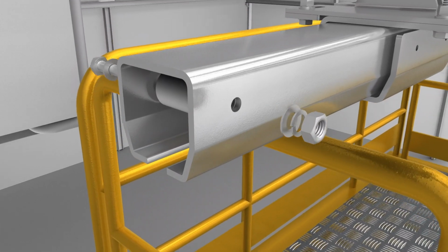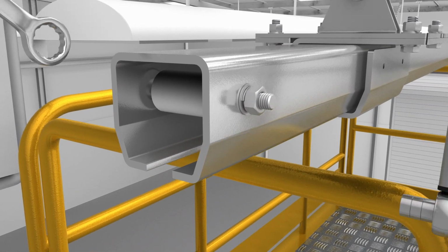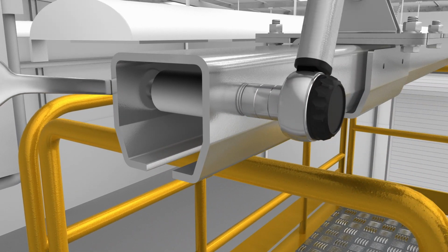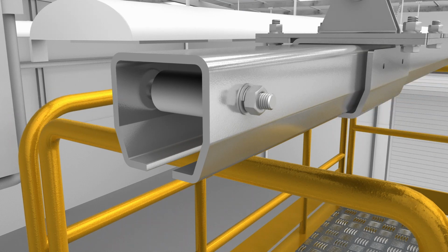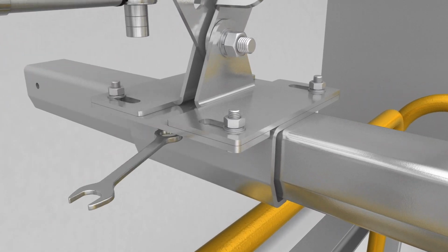For all extremity rigid rail sections, install an end stop buffer and secure into place using an M12 100mm bolt assembly. Tighten all the bolt assemblies to the torque value shown in the torque settings table.